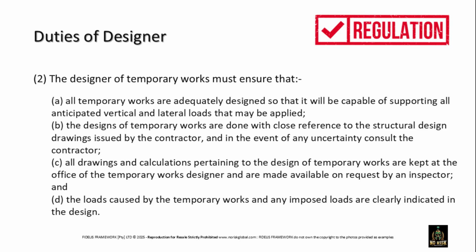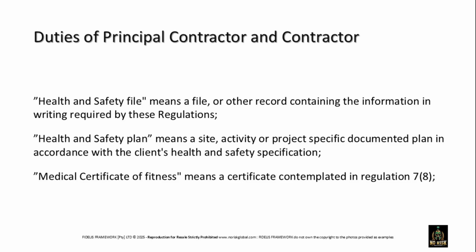Designers of temporary works must ensure designs are capable of supporting loads. They should keep drawings and calculations available for inspection and clearly indicate imposed loads. Health and safety files and plans are essential documents for construction projects. Medical certificates of fitness are required for workers.